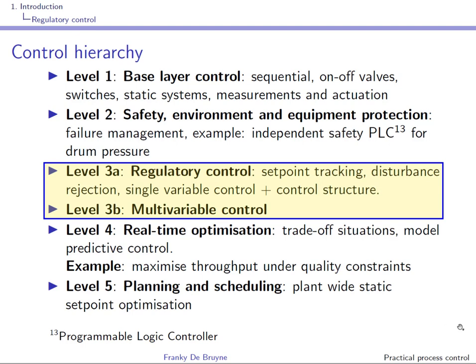The next level is the planning level. This level uses a computer-based management system called Manufacturing Execution System, or MES. This system monitors the plant from raw materials to finished goods so that management can plan and schedule the production. On top of this, you might sometimes find a management level which uses an enterprise resource planning system, or ERP system, for operational management at enterprise level.